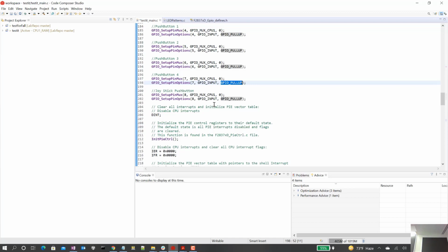Anyway, okay, good. All right, so you'll see in the labs I'll ask you to go to the PinMux table, and that's that sheet that I just showed you, to figure that out. And that's what you always should do. Each lab you should kind of just remember that, okay, we're going to be working with these I/O pins as I start talking about them in the lab. We need to put them in the setting that is needed, like when we get to the serial port setup and all that kind of stuff.